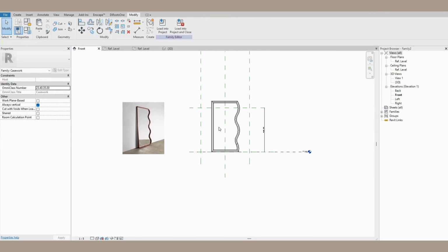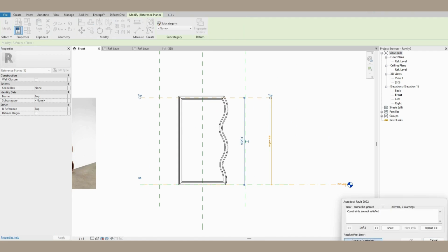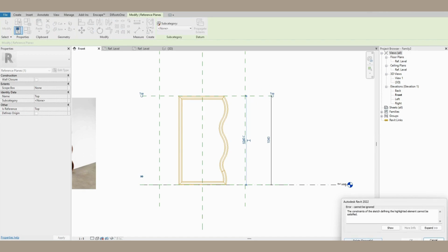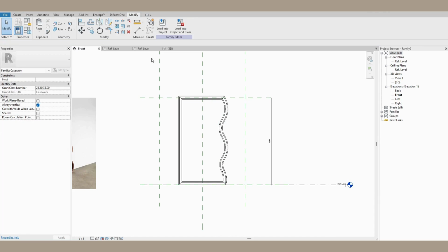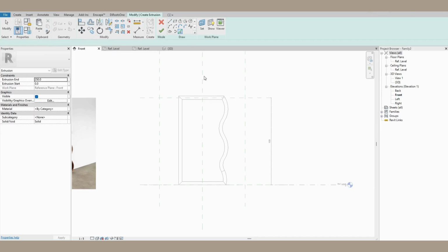Yes, they are very important in Revit, but that's not what we're constraining our drawing to at this point in time. So just go to your front view, click create, and we're just going to create a general extrusion. Normally I like to pick the green line and pick the edges so it draws them for me, but since it is circular and it is a spline tool that we've used to draw, Revit isn't so efficient at picking those kind of edges up.